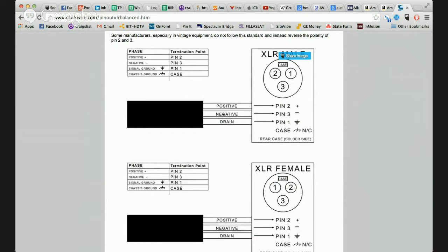Okay, so in a standard audio cable, you've got 3 conductors, is what we call them. Okay, so you've got a positive, a negative, and the drain wire, which in this case would also be called the ground. And this is generally made up of what's called the shield. Okay, that's the strand, not stranded because it's not really stranded together, but there's a bunch of metal strands if you've ever opened up one of these cables.